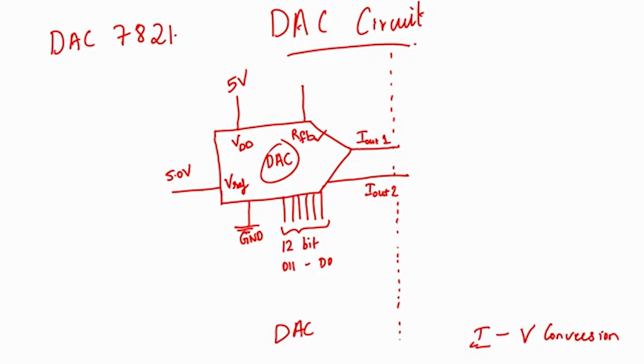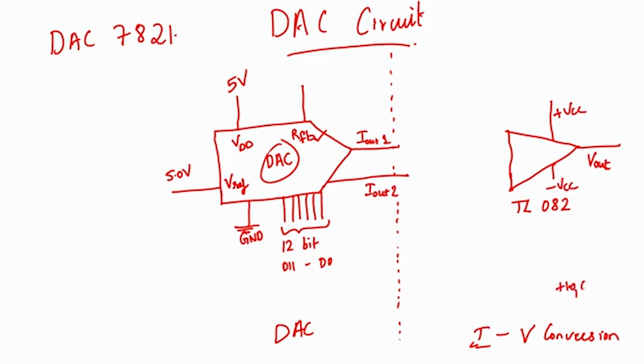So, what do you need to do that? First you put an op amp. On the board we have this TL082 op amp, so we will use that. The op amp will have output V out, and supply rails plus VCC and minus VCC. Ideally this op amp should work from plus 10, ground and minus 10 volt, but we will work it with plus 15, ground and minus 15 volt. It will work in these voltage rails also, as it is designed for sufficient tolerances.